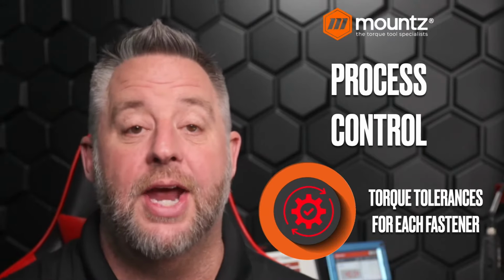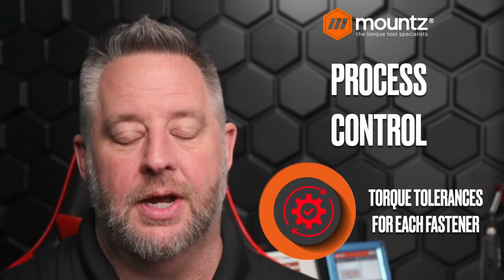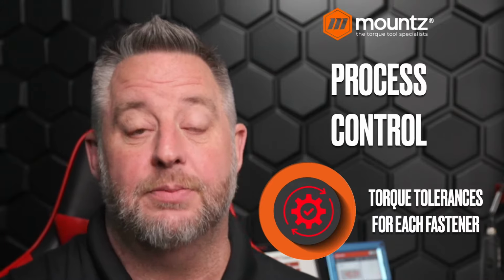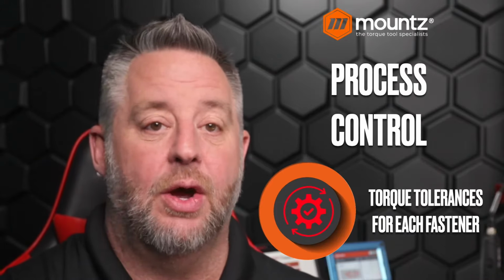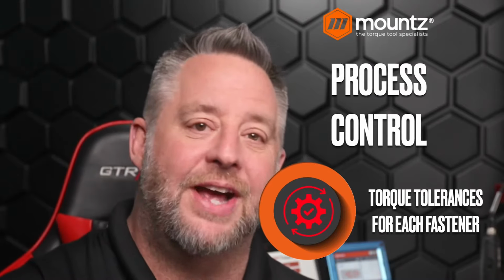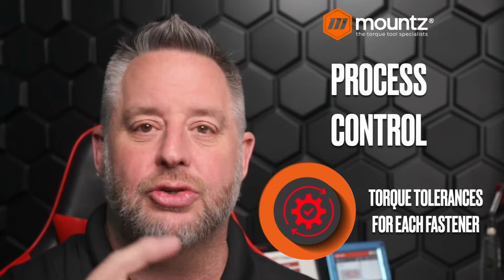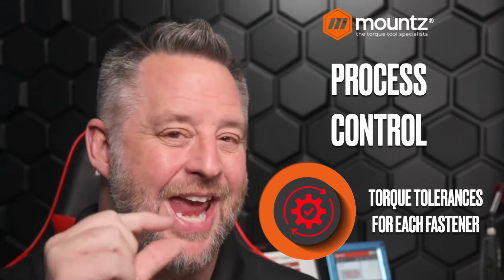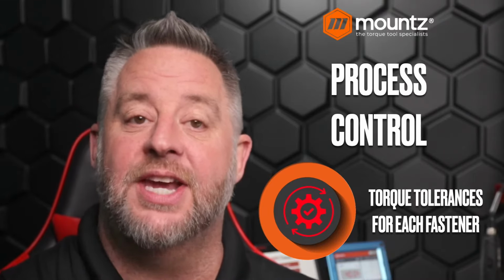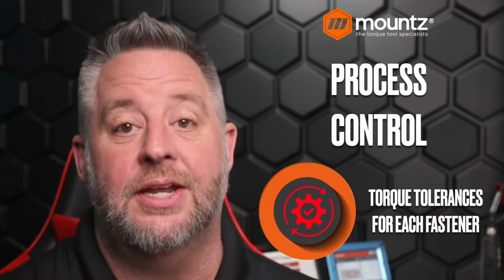So for example, you could have a fastener that has all of the same recommendations for the torque, could be the same size, but the only thing that's different is the length. And if you put that shorter fastener in where it's supposed to be the longer fastener, you could have some issues. So we can control some of those tolerances around a specific fastener. Even though the torque values may be the same, we can detect to make sure that the correct fastener is being used in the correct location.